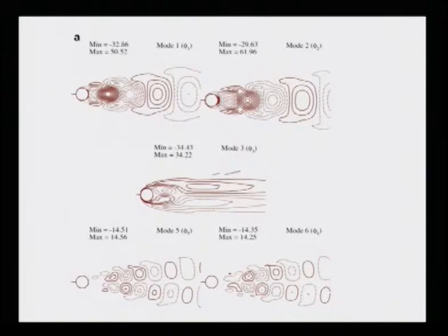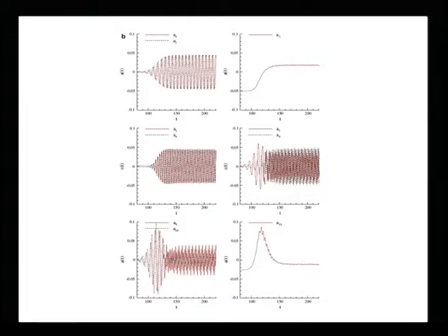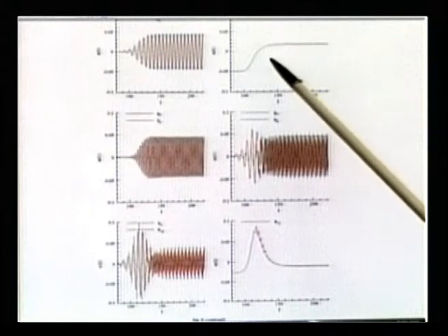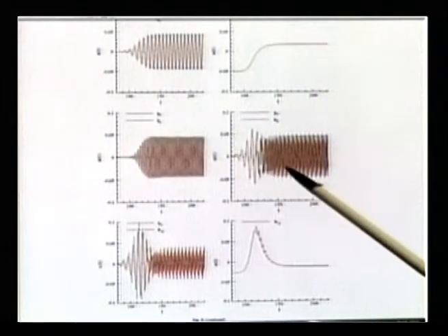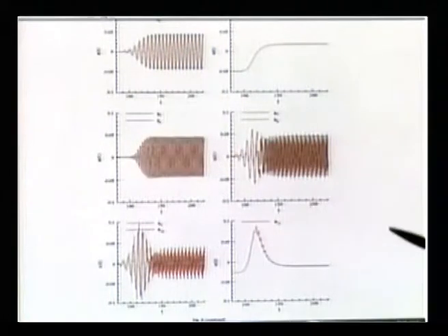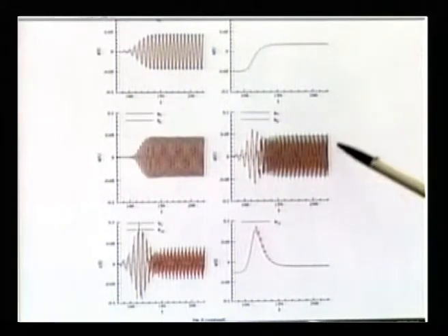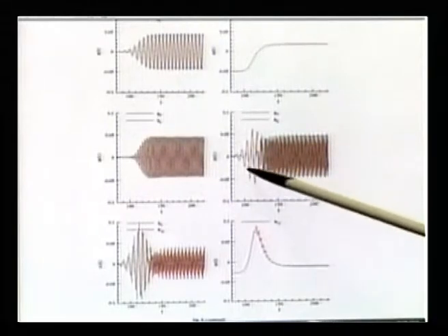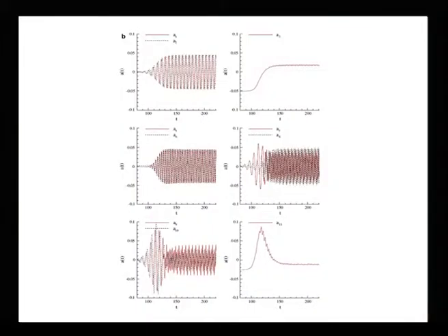So there is no question about it, and these were also the mode shapes that we have seen for flow past a cylinder. We have seen the regular modes 1 and 2, then we have the shift mode, then we have another set of regular modes. This is a very interesting thing you are noticing here: in the end you get to a regular mode, but in the transient phase once again they are dissimilar. The individual components are dissimilar.